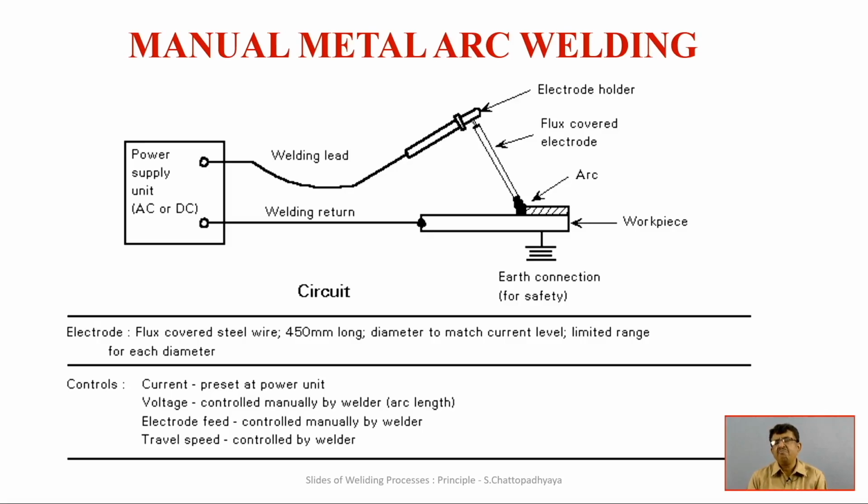These are all four major process control parameters of the weld. And the yield parameters, the destructive parameters, are the tensile strength. That is the most important parameter of welding, how strong the weld is. And next are bead geometries: bead penetration, bead height, and bead reinforcement.